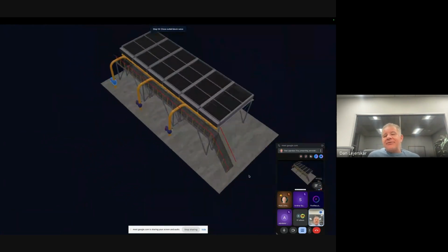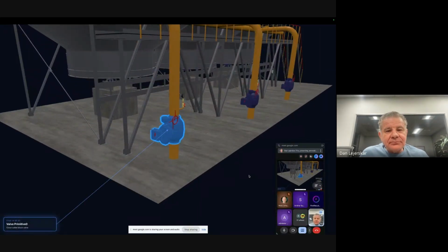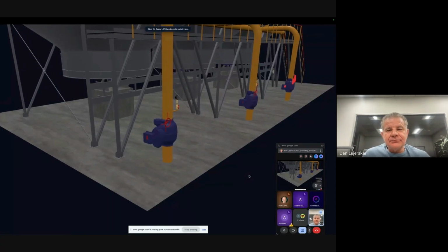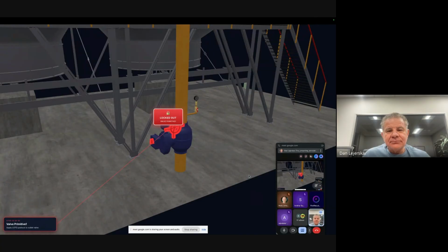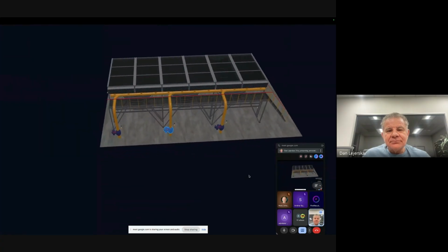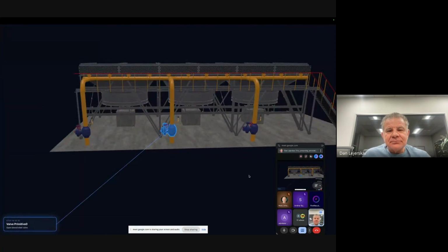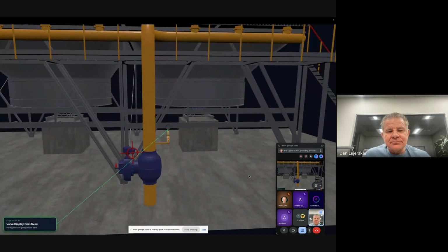So I'm in real time. This is not an animation. Close outlet block valve. Apply LOTO padlock to outlet valve. Open bleed relief valve. Verify pressure gauge reads 0.